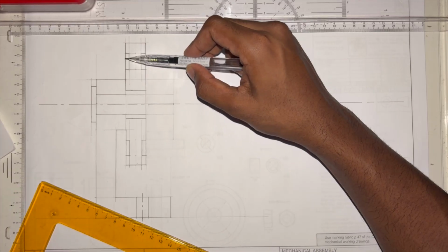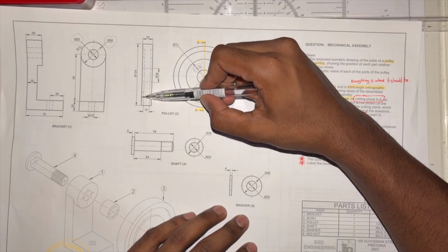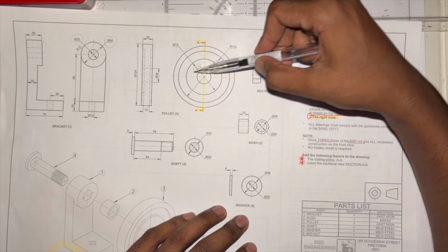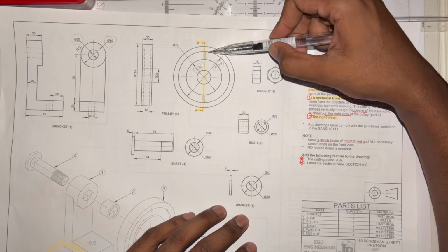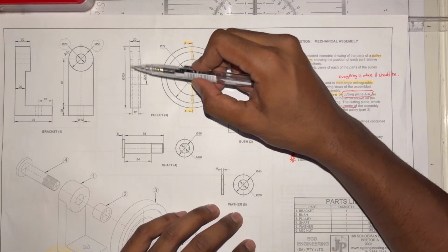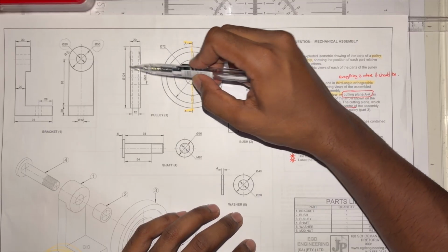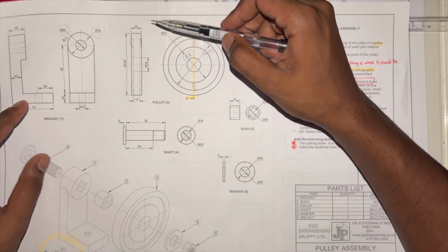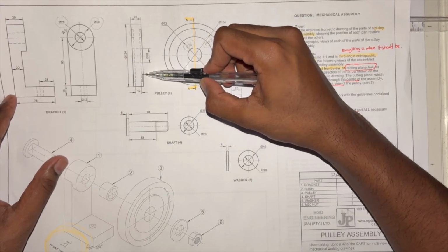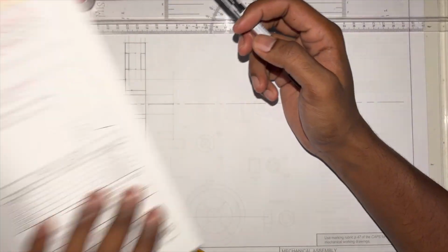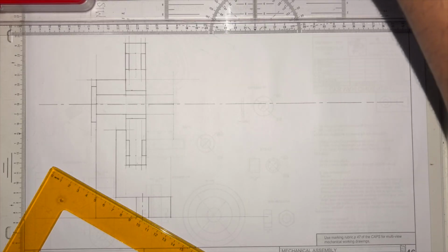Well, here's the answer. When you cut through this and it's shown like this, you can still see the back of the pulley. So we're cutting here, we're looking, this is going to be hollow, that's going to be hollow there, but we're looking at the back of it. So this has to be a solid line. If I had a 3D, I would show you. Maybe I'll insert that later on, use some creative magic there and show you guys. But this is a solid line. It has to be a solid line. Let's continue.